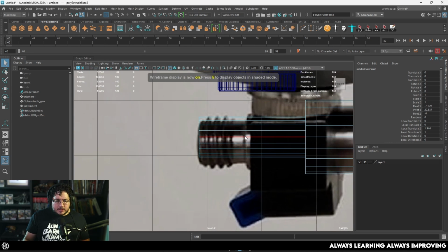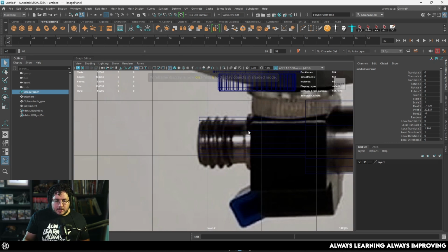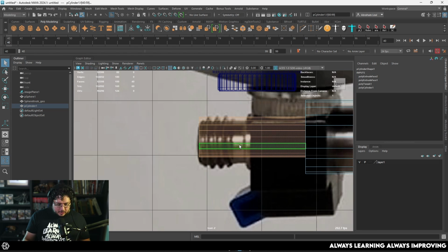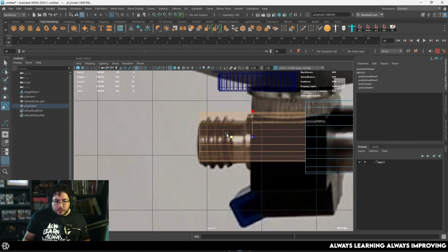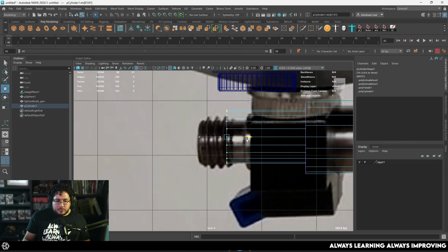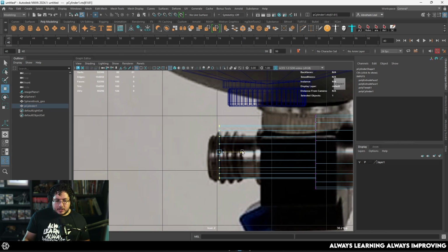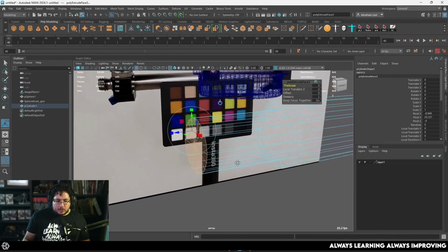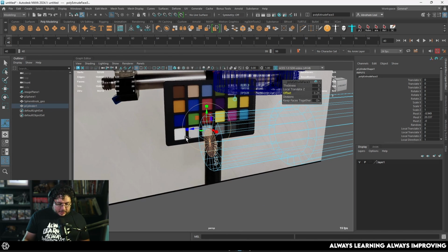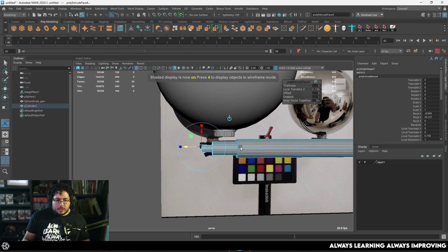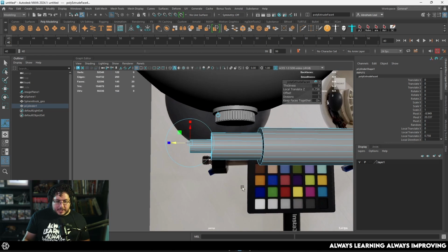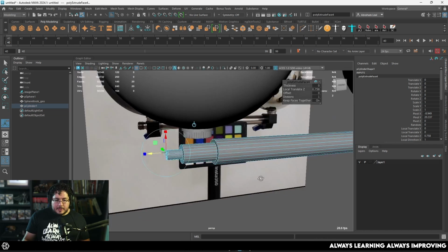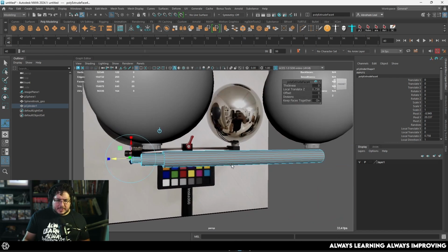Now, one thing that I am noticing is that it changes diameter right around there. So I'm going to grab all of my faces here. With R, I'm going to press Control and the green square right there so that we scale everywhere. There we go. Grab all of this vertex, push them in a little bit more. As you can see, these guys are a little bit after they finish this spot right there. So right around there. Remember that the image is in a little bit of perspective. So we should take that into account. We're going to offset this, Control E, and push this out. So that gives me enough room to have that sort of black piece that we're going to add in just a second. And still have the rest of the elements.